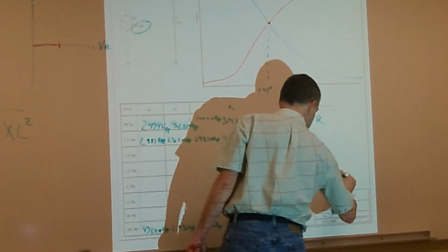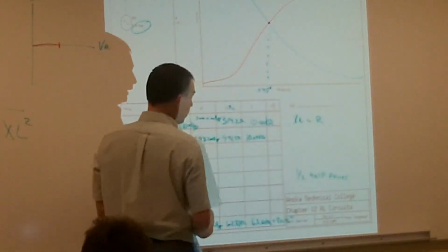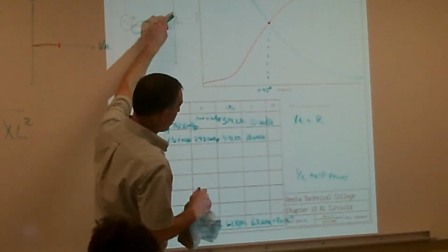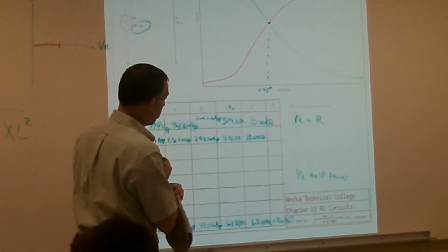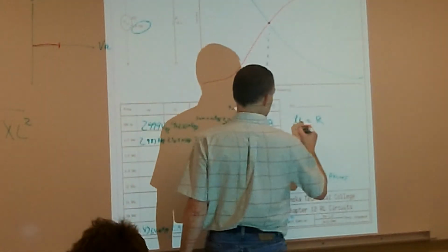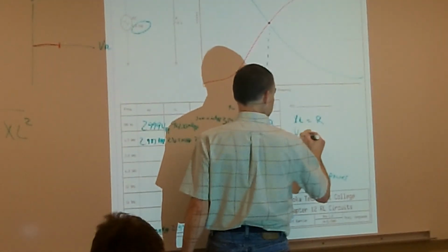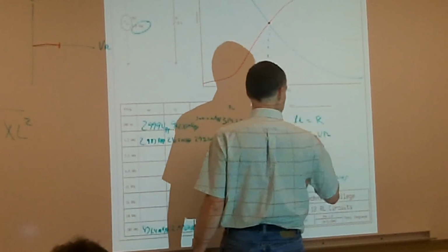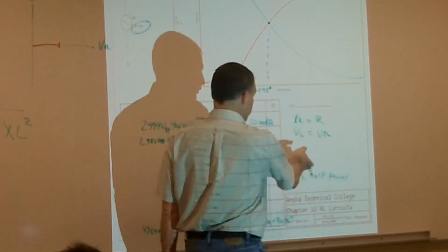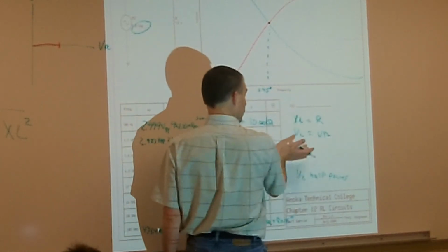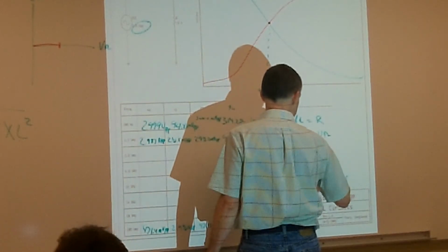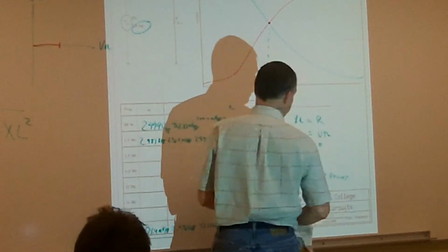Good. And that's our big term that we use. That's typically where we get our maximum power transfer too. That's when we get our maximum amount of power going across either one of our components. So X of L equals R. Some of the other ones are PL equals PR. All those component values are equal to the same. Plus 45 degrees, I'm at my half power.